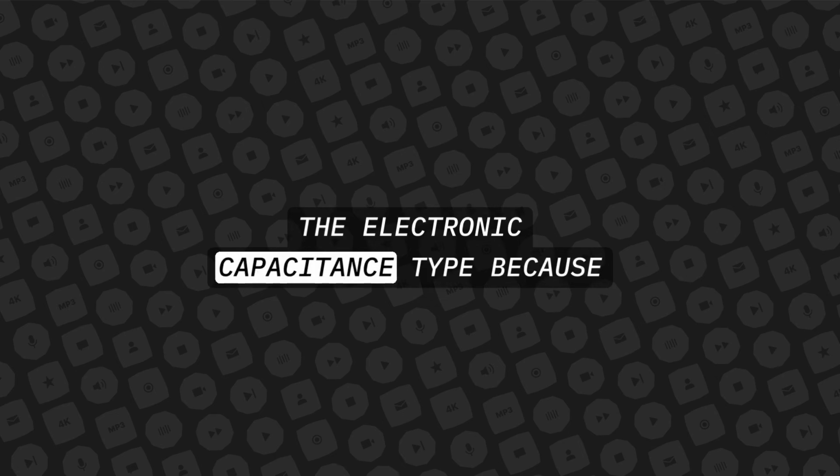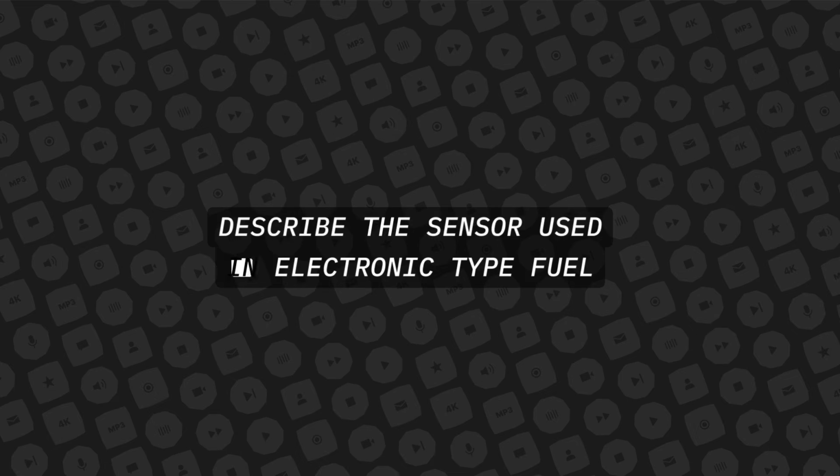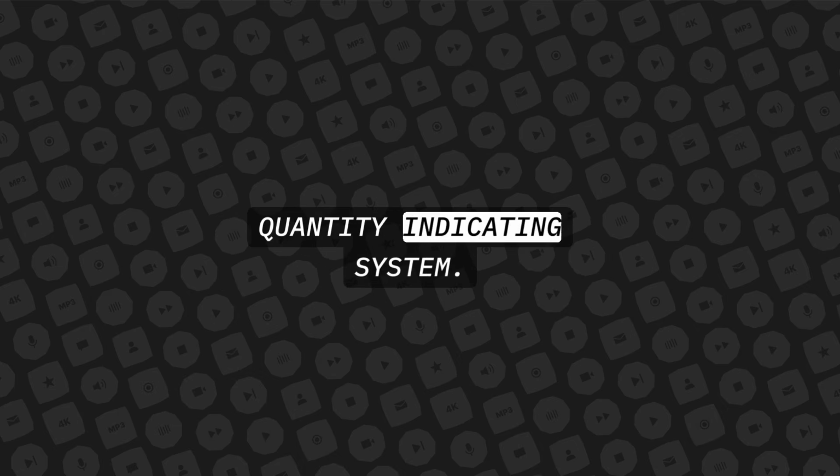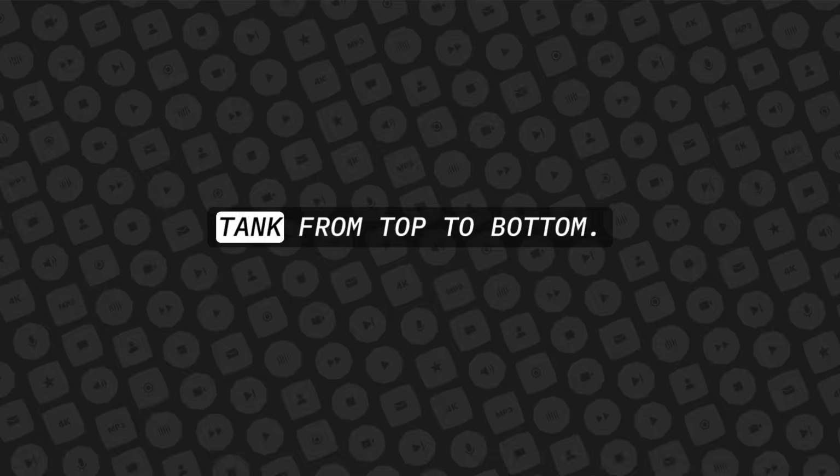The electronic capacitance type, because it measures by weight. Describe the sensor used in an electronic type fuel quantity indicating system. It is a tubular capacitor that extends across the tank from top to bottom.